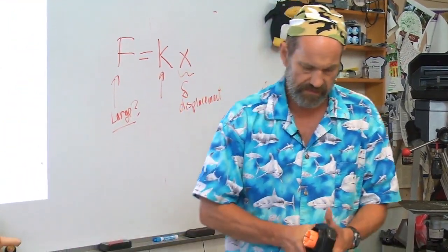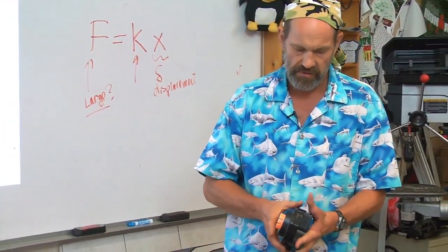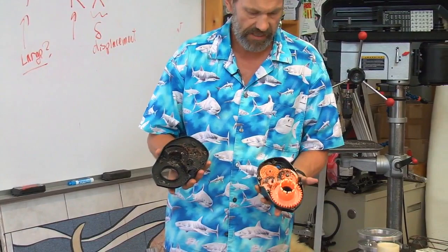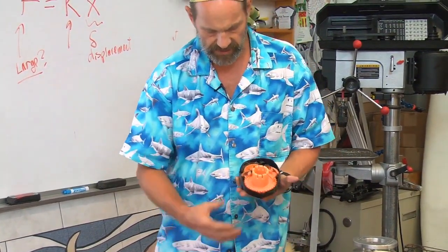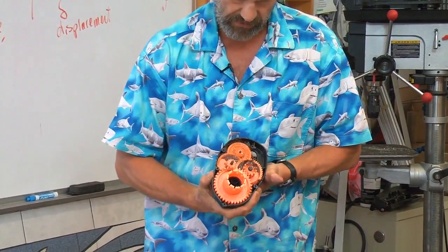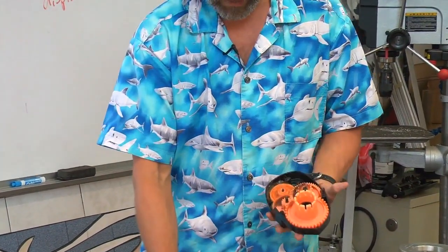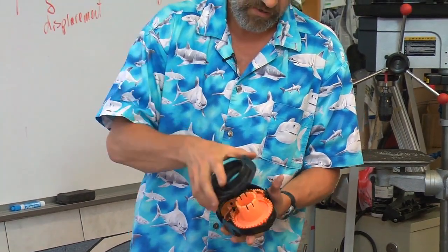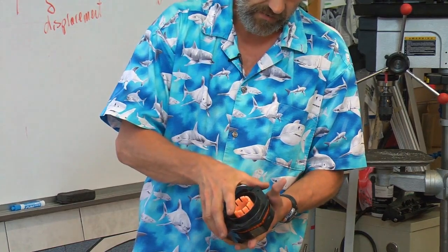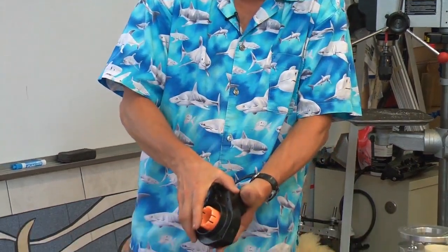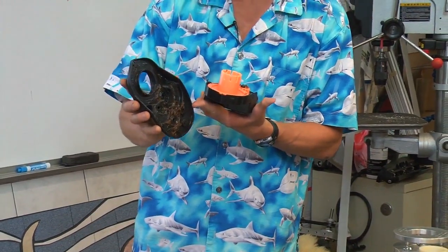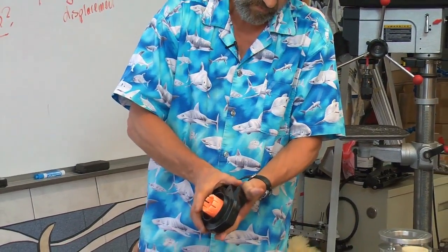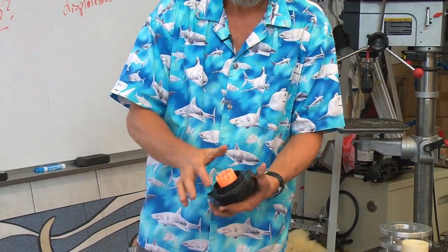So for example, we showed last time, when we were talking about gears, this modular transmission, and how the housing itself with these finite thin thickness walls, which, so you see, are a little soft, and the shaft features for the gears, and then the mating features on this part, I bring them together, and they don't exactly fit. They fit pretty close. There's some lead-in tapers, so it gets things reasonably closely aligned, and then when you push on them, it snaps together.